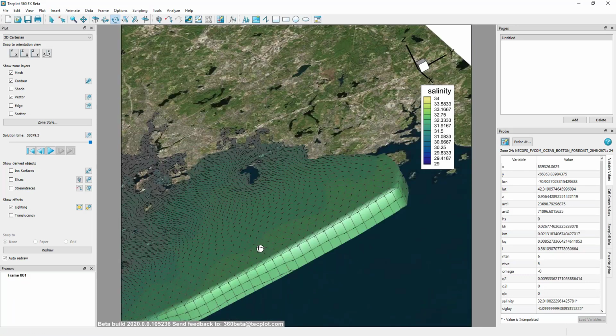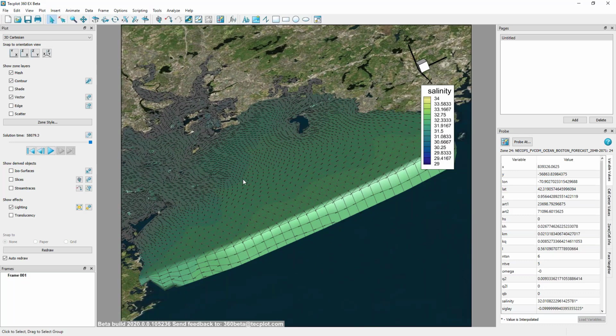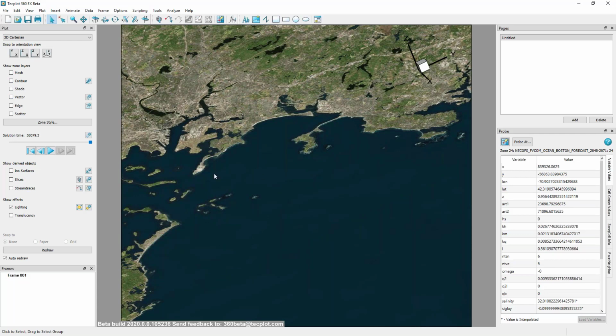let me just make some adjustments here. There we go. With the contour toggled on for the entire zone, it wraps around here and cuts off our view inside the fluid volume a little bit. So we can't see what's happening in there. We're only seeing what's happening on the exterior. So if I toggle off these zone layers, to clean up the plot and instead use the isosurfaces.